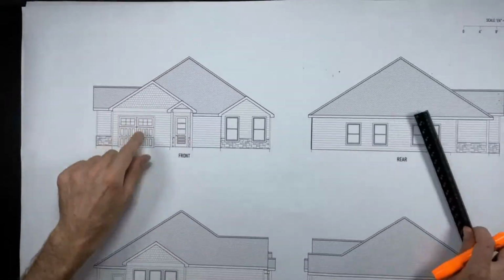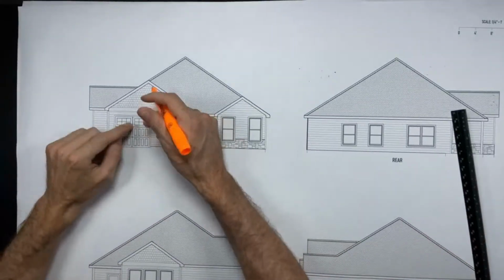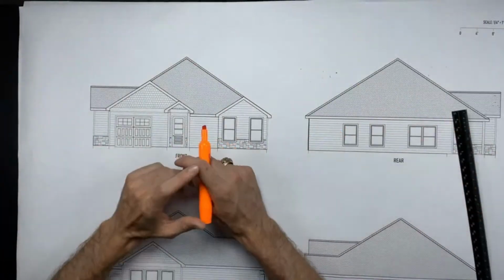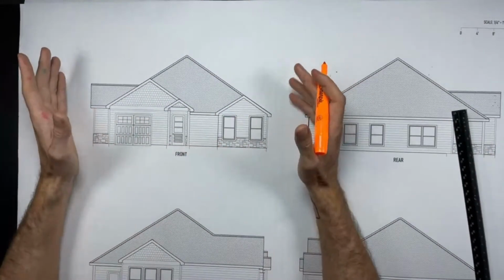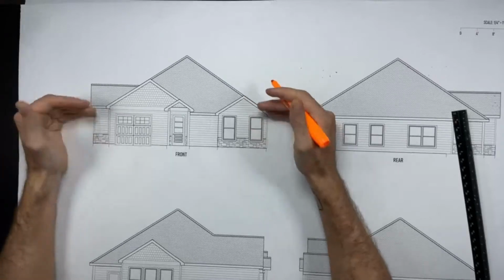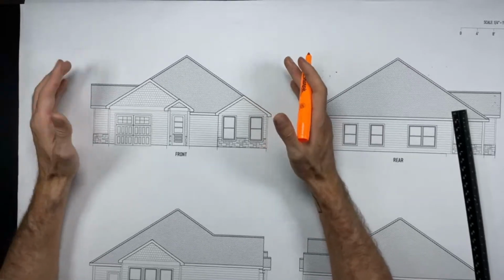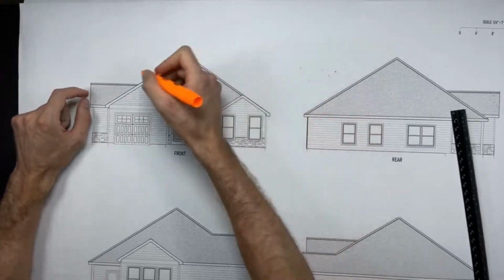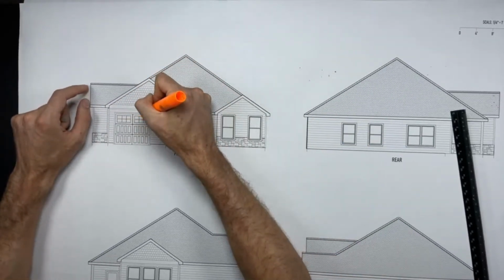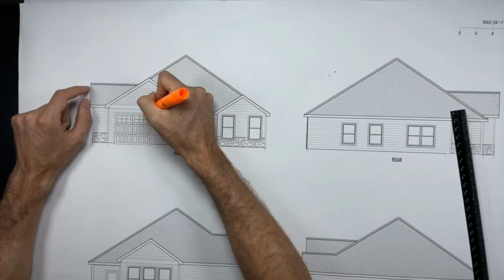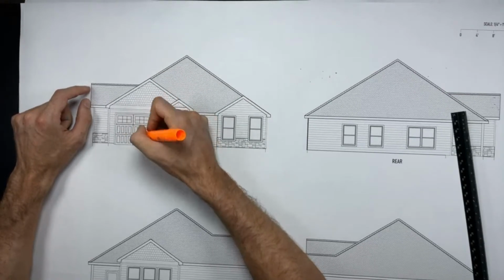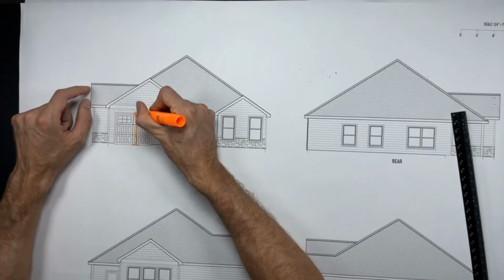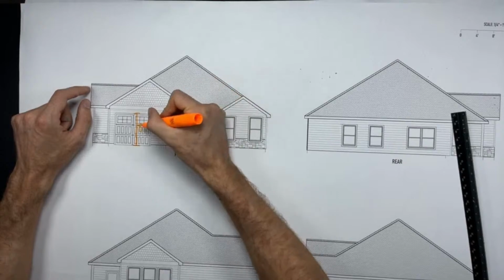Okay, so elevation shot. For example, let's assume there's just some crazy amount of weight on this garage door, or the garage door is super wide or whatever. And for whatever reason, we need like an 18-inch tall or a 24-inch tall LVL header over this garage door. What people forget sometimes is that the garage header height has to be a certain height. If this is an 8-foot door, that means from the bottom of the garage floor, which has been sloped, right? See the door drops. Garage to here, let's say that's 8 feet.